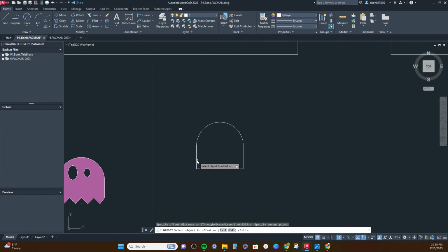You're going to click for an offset 3 times, and you're going to offset 1/32 of an inch. Enter. And then you're going to click the line again. Click over to place it. Whoa, that didn't do it right. Sorry about that. I'm going to Control Z, and I have to hit Escape. I'm going to Control Z and back up. This didn't offset the right way, and I'm not going to stop now.